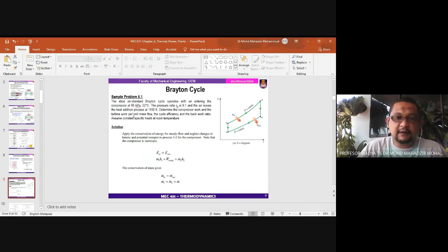Okay, this is the air standard ideal cycle. That means this cycle uses air. When it uses air, as I have told you, you have to use the equations to make this analysis, or you have to assume this is the air standard cycle, so use the ideal gas approach to do this analysis. So this is a TS diagram for this Brayton cycle. There are four processes here.